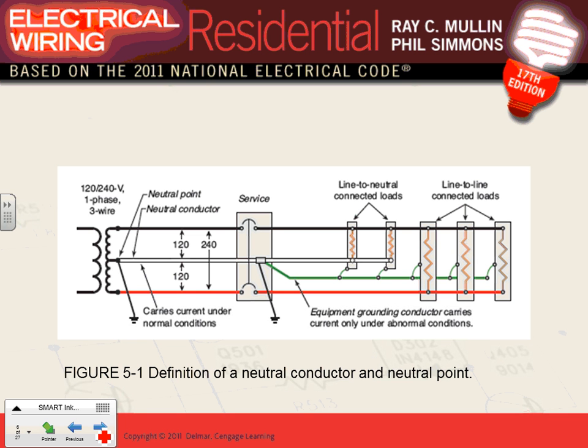Here's what we're talking about, color-coded. This is a 120/240 system, as you can see, because we're doing residential. I can't emphasize this enough. I've had students in the past, guys, reach the 5th year, they're graduating, and they don't understand this when we go to the 3-phase system. This is a single-phase system. When you have a single-phase system, there are 2 types of loads you can put on it: line to neutral or line to line, right?